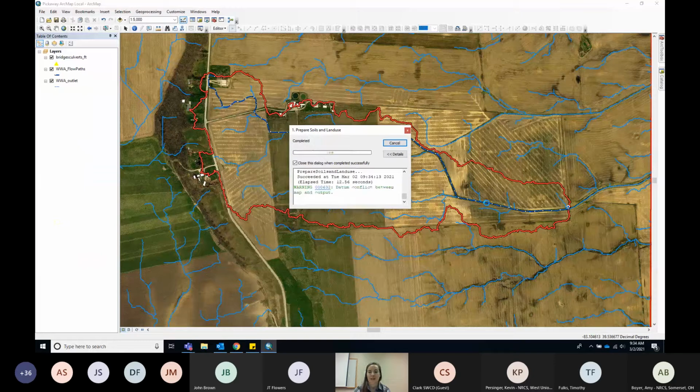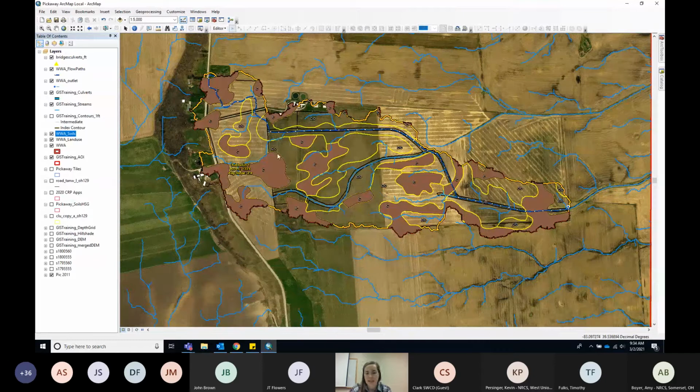These tend to run a lot faster. So some of these filled in with their soil types and some of them didn't, and that's because they may have 2 options. So a lot of times if the soil is drained, we use the lesser runoff number.